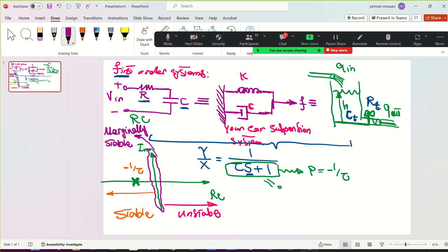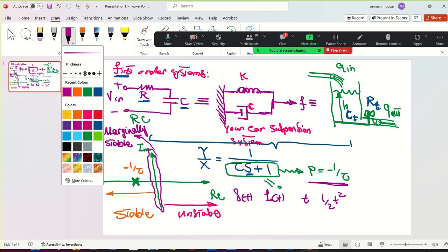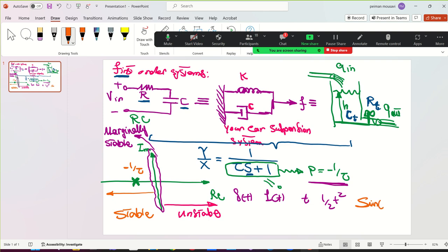Everyone got it? So the first order system you see here that they are dynamically equal has 1 pole in the left hand side, so it means that it's stable. What I'm going to do, I'm going to apply impulse as I promised you after driving and showing it all of them like this. Unit step, ramp, parabolic input in the Simulink, and in math at first, then Simulink. And finally, I'm going to apply a harmonic input sine omega t for the first time. To teach you frequency response is technical name.